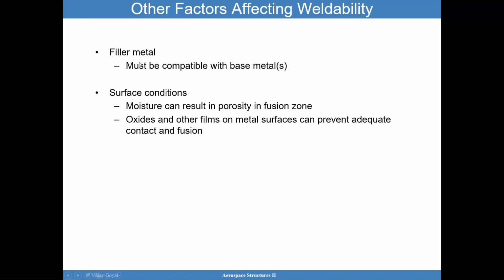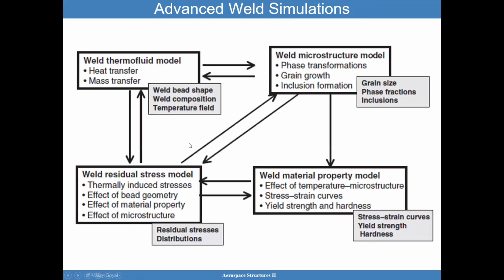Continuing here, the filler material must be compatible with the base metals. Surface conditions can be quite important. If you have moisture, that can result in porosity, and oxides and other films can prevent adequate contact and fusion. There are a lot of advanced weld simulations that exist that I think can be used. Some of them are quite complex. Some of them are good top-level types of analyses. When it comes to welds, it's sometimes a good idea to start simple, do a lot of testing, learn about the quality of the welds, and increase your confidence in the allowables.